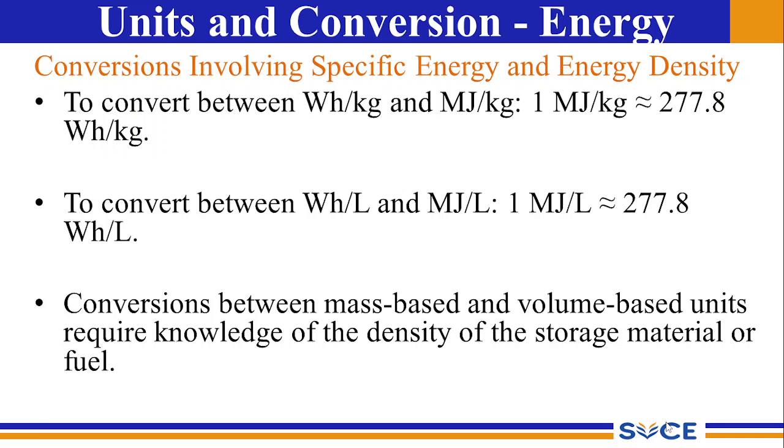A key important thing is that when you're converting mass-based to volume-based units, you need knowledge of the density of the storage medium or fuel. The first line talks about watt hour per kg, whereas the second line talks about watt hour per liter. Different materials have different densities.